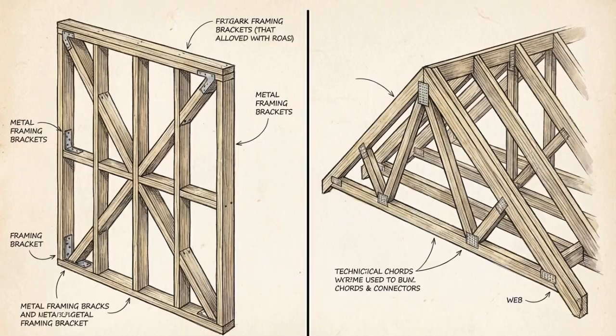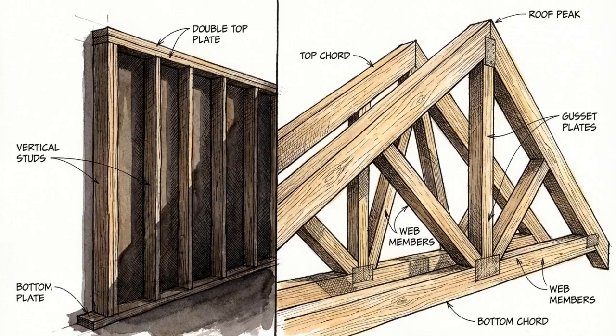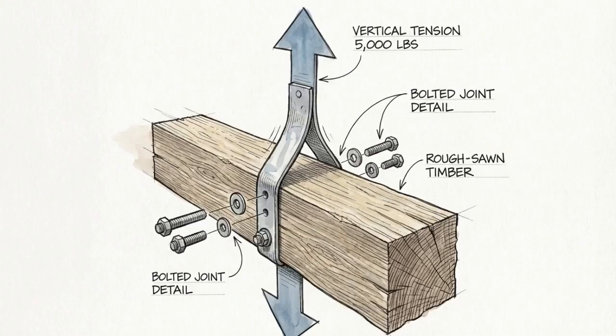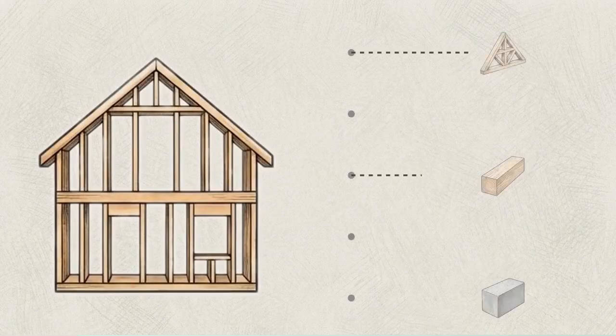It is important to distinguish between general wall bracing and truss bracing. Bracing for trussed roofs is governed by AS 4440, and these two standards should never be cross-applied. Vertical uplift forces are managed through a continuous tie-down chain. This tie-down chain creates a direct load path from roof batten to the footing.